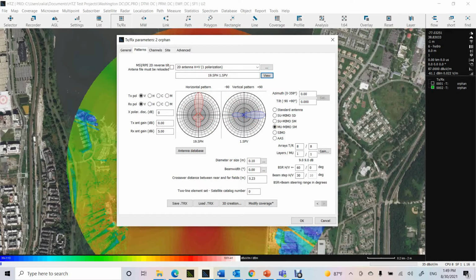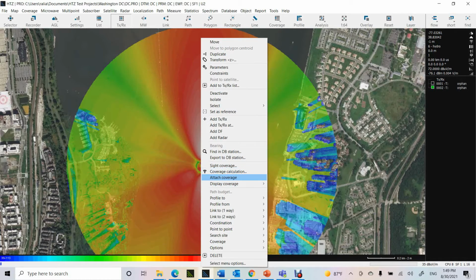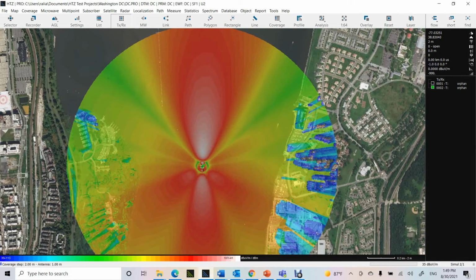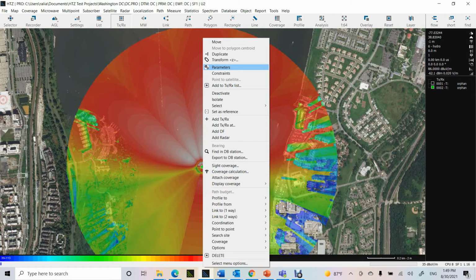And then let's verify that in the coverage as well. So I said okay, let's run the coverage again for 1 kilometer. You see that I have an angle of 60 degrees for my aperture, plus and minus 60 degrees. And then I will have a 30-degree step, okay? So on the right side, which is plus 60 degrees, I have 1 and 2, and on the left I have 1 and 2. Okay, this is as far as your horizontal beamforming.